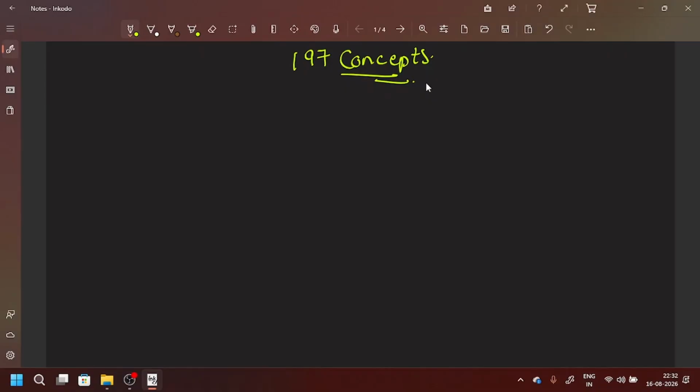So I hope you are familiar with the RC Phase Shift Oscillator, but let's just take a brief recap of the circuit. The circuit basically has three RC sections, that is, resistor and capacitor sections, and each section will give you a phase shift of 60 degrees. And for us to get sustained oscillations, we need either a rotation of 360 degrees or 0 degrees, and definitely we need the gain to be greater than 1.